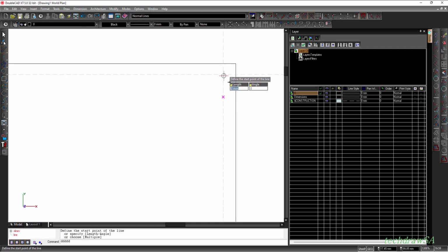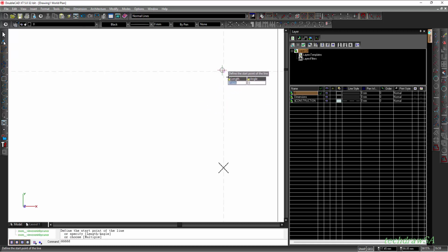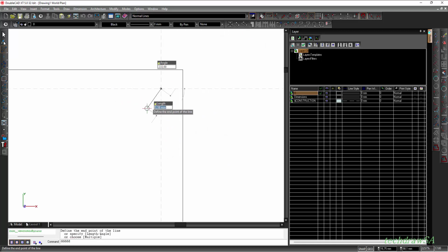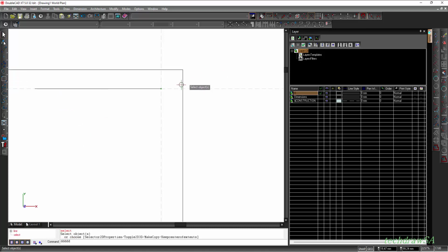And once again, because I have created an intersection there, you will see my endpoint is active, my intersection is active over there. So that is what I need. And I'm going to deselect that quadrant. I don't need that. So now I can just click there and drag it. And if I hold shift, I can drag it as far as I want. Press escape out of that.